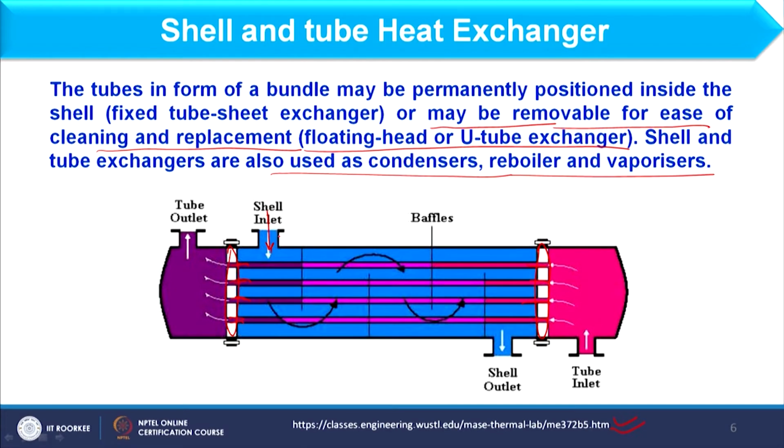Okay, shell inlet is here, exit shell nozzle is here. So, you can see whatever fluid is moving in this shell, it will not interact with that available in the tube side, because tube side inlet pipe is there and outlet pipe or outlet nozzle is here. Okay. So, you can see the tube sheet purpose is to hold the tubes as well as to separate the liquid of shell and tube side.